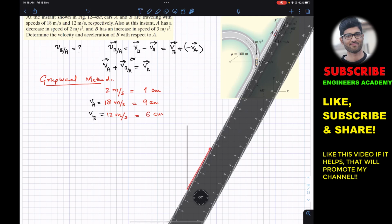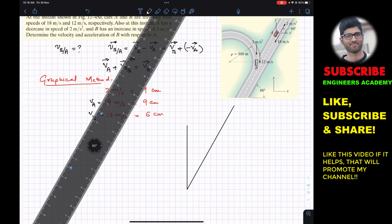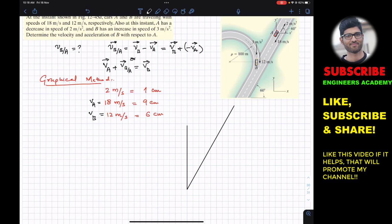So from here to here, let's say this is my 9 centimeter line. Now this is my V_B equal to 12 meters per second. This is my V_A, but since V_A is acting in the downward direction, and we need to subtract it by the head to tail rule, we need to subtract V_A.